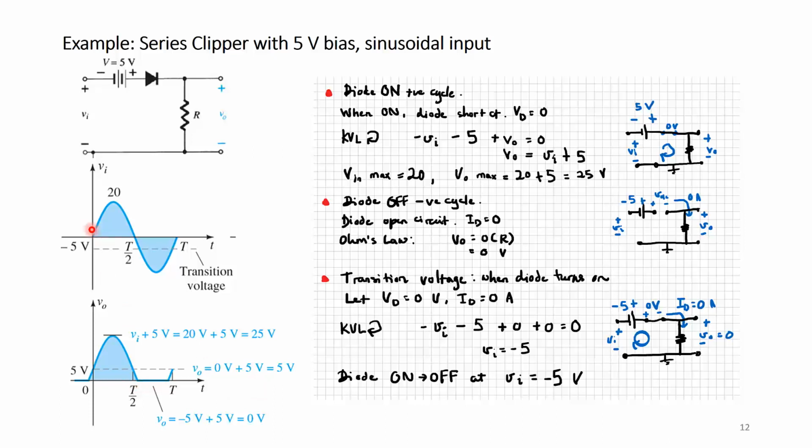So again, if I have a repeating cycle of sinusoidal going up and down, I'm going to have 0 volts when diode is not conducting. And then it becomes positive before 0 time, and then it goes back down to 0 right after T/2 is reached, and before time T, it will start to imitate V in with an additional 5 volts again.